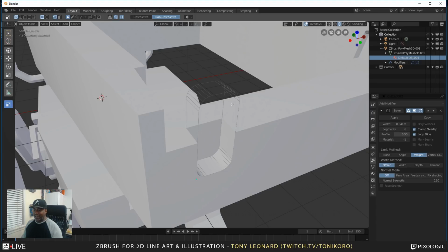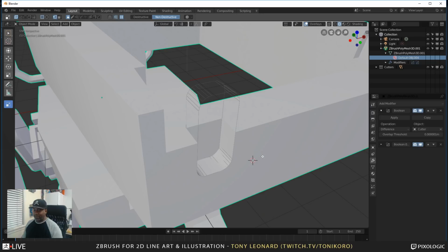I'm going to leave this unhidden so you can just see the shape, but if I select this shape again and I hit Control and start cutting and push this inward, I'm going to hold the shape, hit B just like last time and create the same profile, right? Right clicking again, and then I'm going to hold and actually just tap the Q key, which creates another bevel in the opposite direction. If I hit B again, I can actually change the width of that bevel on the inside.